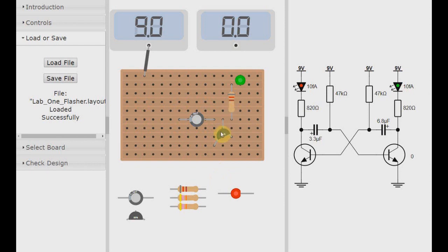And then the resistor, the collector of this transistor, and the positive terminal of this capacitor would all be connected together along this row of the veroboard. The problem is that the positive terminal of the capacitor is also connected together because there is a copper track going all along here. What can we do about that?